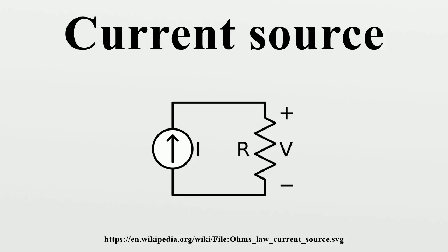Zener diode current source. In this bipolar junction transistor implementation of the general idea above, a Zener voltage stabilizer drives an emitter follower loaded by a constant emitter resistor sensing the load current. The external load of this current source is connected to the collector so that almost the same current flows through it and the emitter resistor.